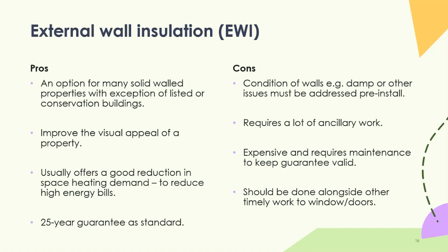The outside finish will need to be maintained just the same as any rendered finish will need to be maintained. The last point is important there, that the windows where you're introducing external solid wall insulation should be moved into the insulation layer. So that's the windows,